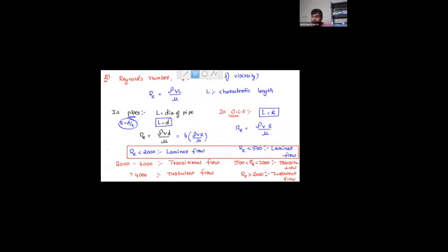That's it. But anyways, in the case of the open channel flow, we don't discuss about the Reynolds number much. You know that. Which force is a major force here? Gravity force. But we must remember, when do you say laminar flow in pipes? In the case of pipes, RE less than 2000, and in the case of the open channel flow, RE less than 500. Then we can say it as a laminar flow.